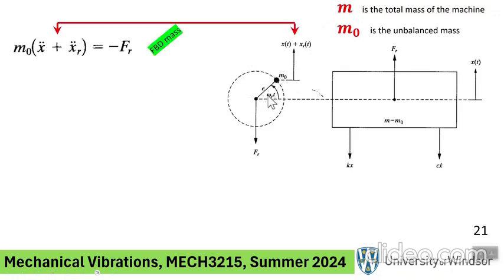All right, let's look at the diagram on the left. Look at what I've done. I have replaced the rotating component with its force on the box, Fr. And because these are internal, for the rotating mass itself, Fr is pointed down. What I'm assuming here is that the force on the box, which is making it go up, is Fr, and therefore the force on the mass at that pin location is Fr pointing down.